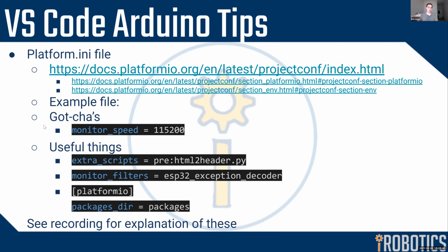So the main gotcha, I think, is this monitor speed thing. This is just the serial monitor. By default, it's 9600 baud, but I generally use a bunch of other ones. So you've got to put monitor_speed = in that file to tell it, when you open the serial monitor, I want you to use whatever speed you say in Serial.begin. It just has to match.